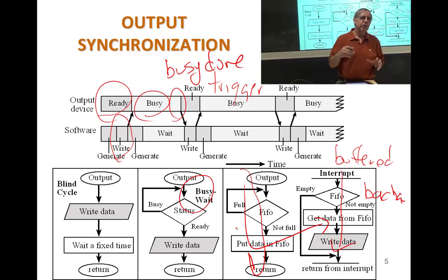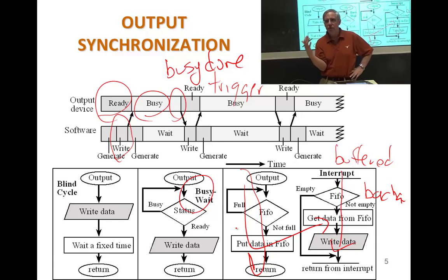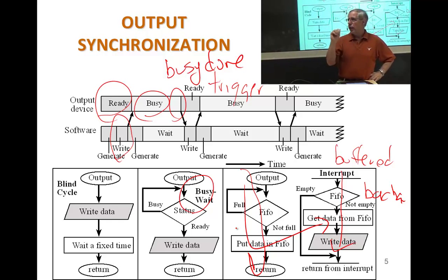But we'll use global variables during the debugging phase. Like I like to count the number of interrupts. I'll just add a global variable that says how many interrupts I have. So when it crashes, I can look at that global variable. Because after a hard fault, the global variables are still there. So you can look at what your global variables are at the time of a hard fault to see how many interrupts it had before it crashed. Did I answer your question?